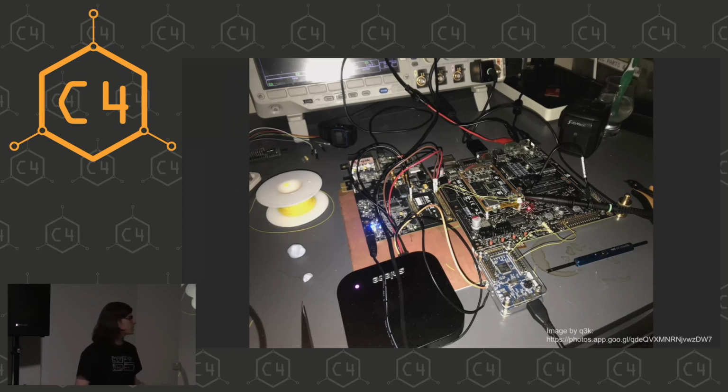We didn't know, for example, for the main CPU or the GPU at this point in the boot process, we weren't even sure that this is the right voltage rail. Because, for example, if you imagine the amount of voltage rails that you have on this chip, they are used for all kinds of stuff in the chip. Maybe for the clock generation circuit. Maybe this gets its own voltage. If we knock out the clock generation, we of course knock out the CPU as well. But this is not what we want.